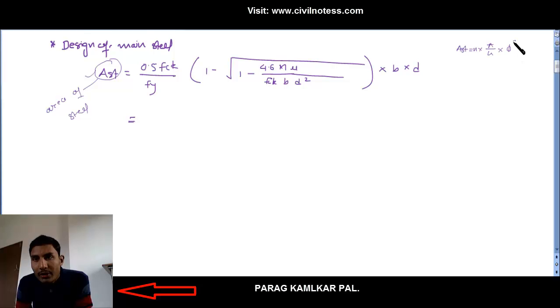With respect to that, if you put a particular diameter, or instead Ast, you can know the number of bars you wanted to provide. Okay, pi by 4, there is nothing you have to change over there. You can get the diameter value. If you put the diameter value, you get the number. Between the two, you have to make sure that you put only one value, then you get the other value.